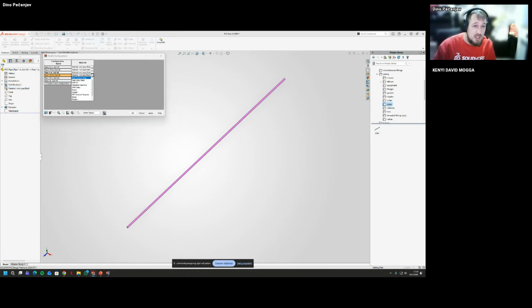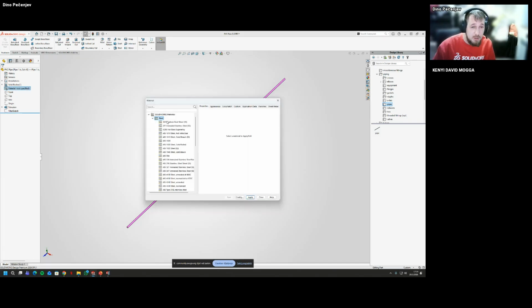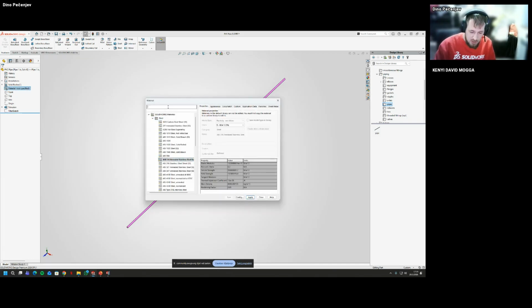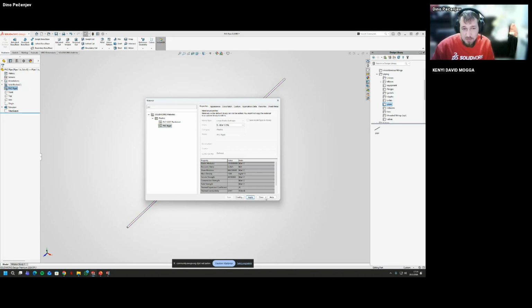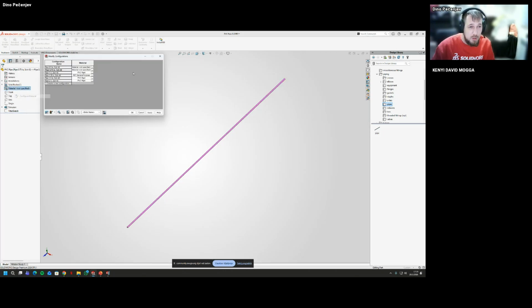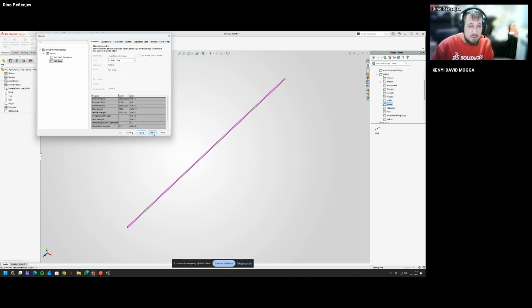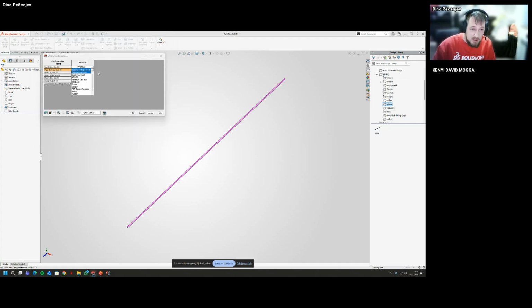I can have multiple things in the same file, but it's just going to use the exact configuration of the pipe regarding the connecting flanges. And I'm just going to double check here. Okay, I'm just going to quickly do configure material. I'm going to say, yeah, browse for more. So PVC rigids, but okay, just so it could be shown.